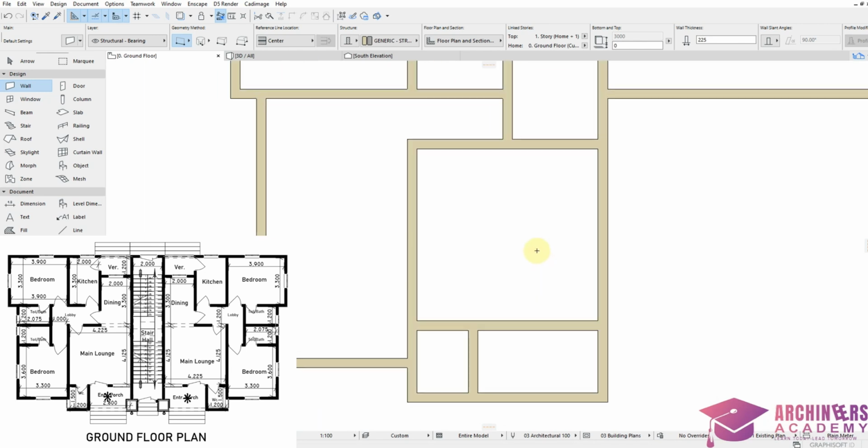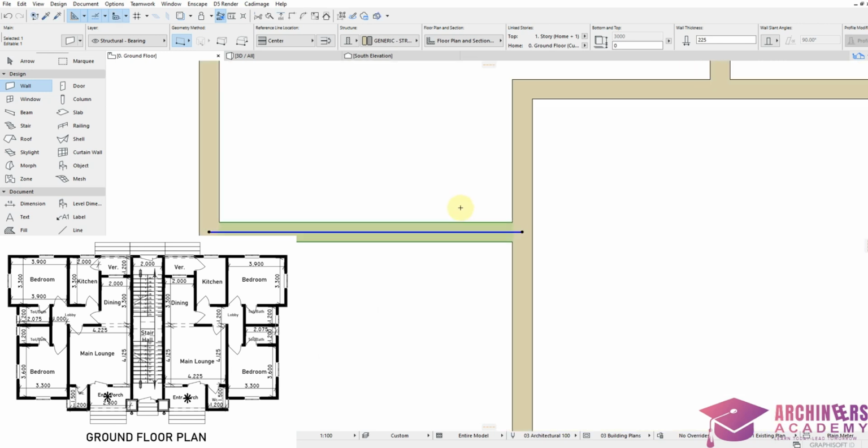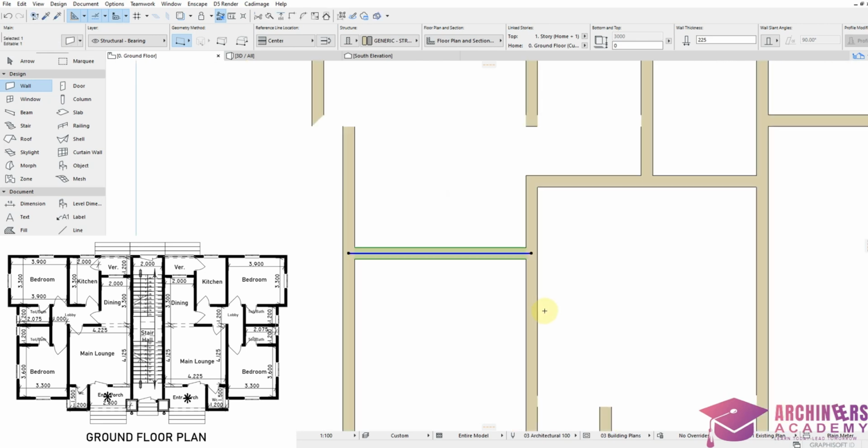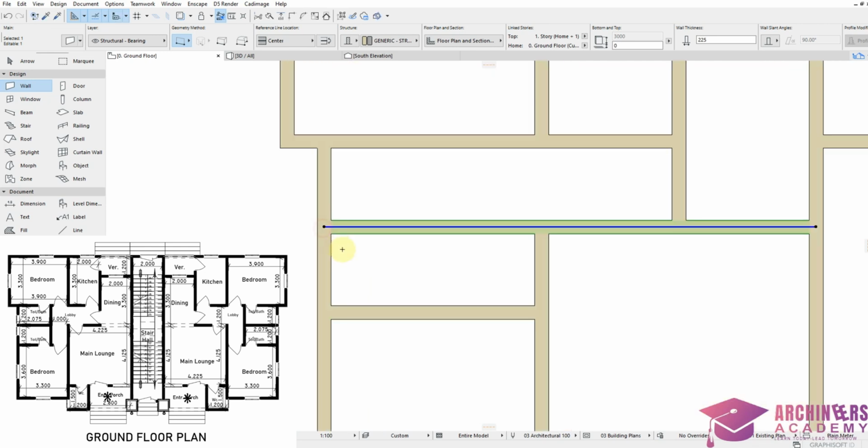Alright, so we're making progress. Now the width of this is 3,600. Rather the length 3,600. Then we'll add the thickness of the wall. Then we have 2 bedrooms left, which is 1,200. Control Shift D. We have 1,200. We'll add the thickness again.